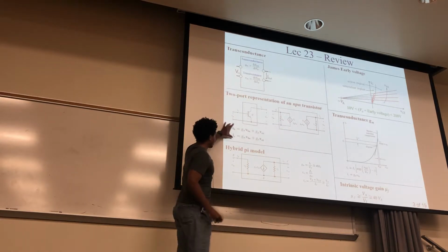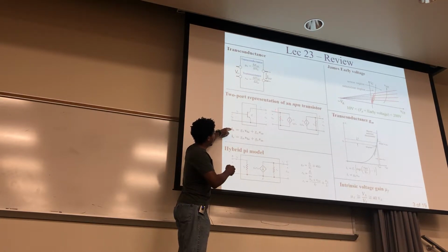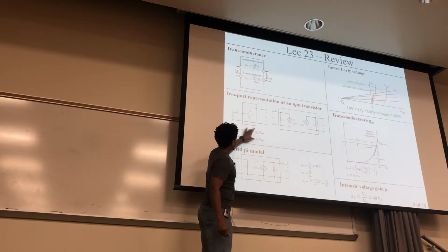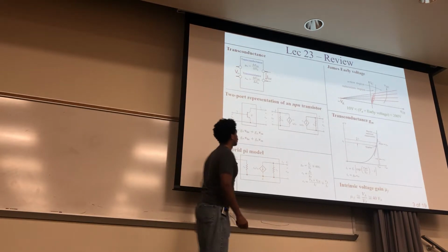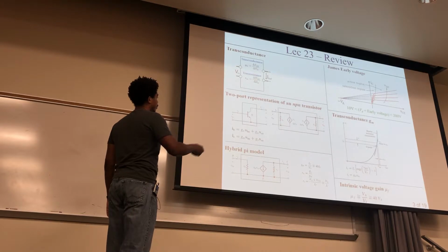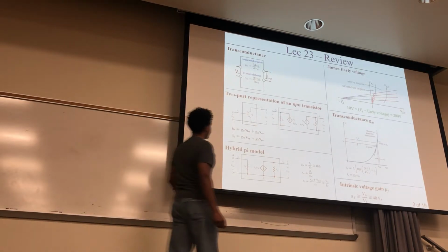And then these right here, those were the Y parameters, okay? So it's the current right here coming in, for the input port, and then you have this current on the output right here, and it's a function of these voltages inside, the BEs and the CEs, of this transistor inside.